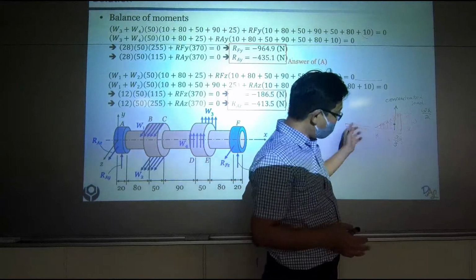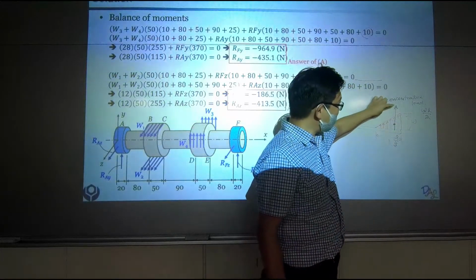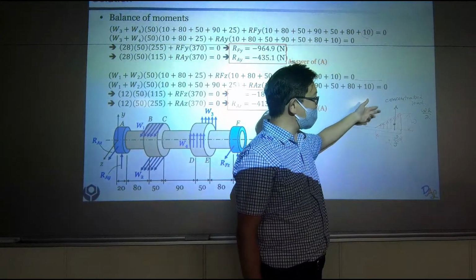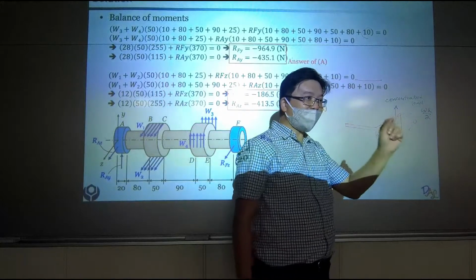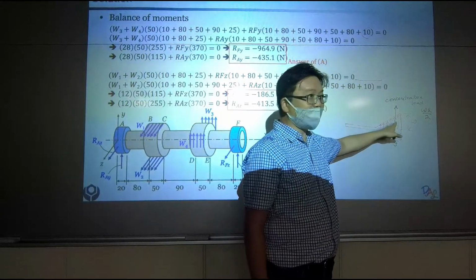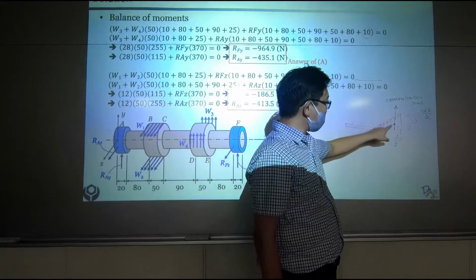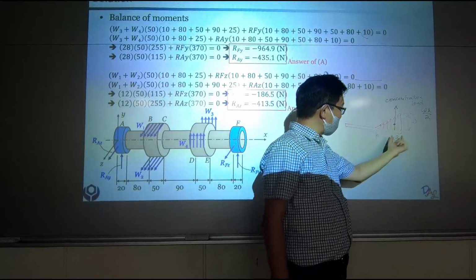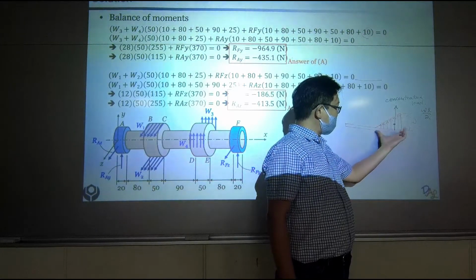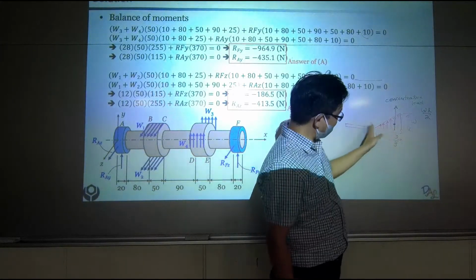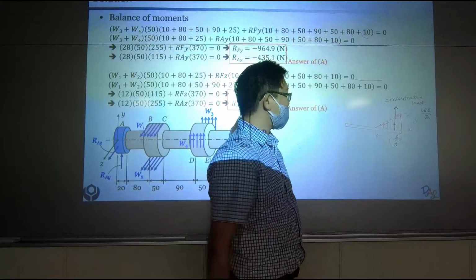So for any shape, just calculate the area. Then you can convert this into a concentrated load. And where is the position of it? Right at the center of the geometry. So for triangles, the center of the geometry is at 1/3 of the distance along one direction. Thank you, very good.